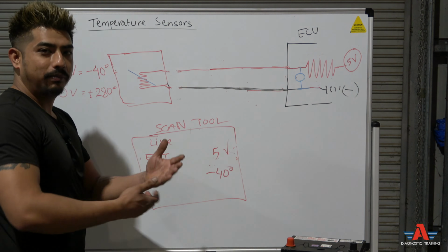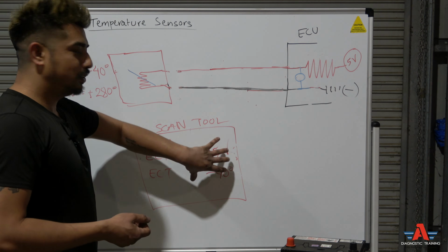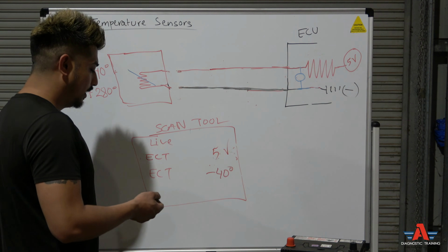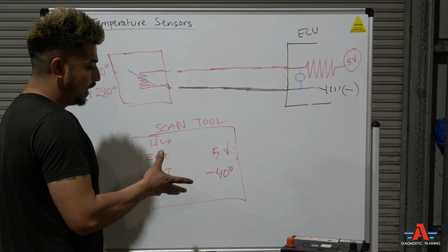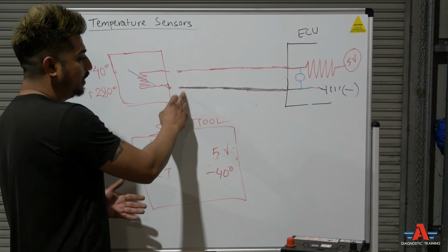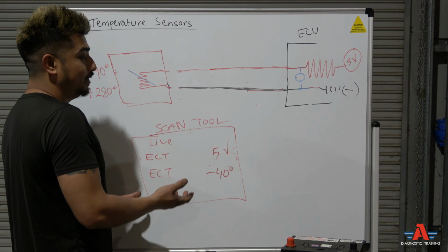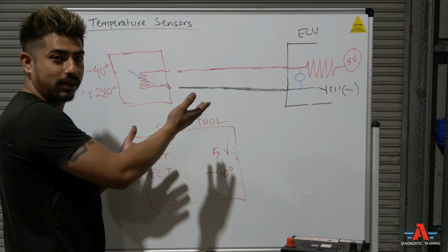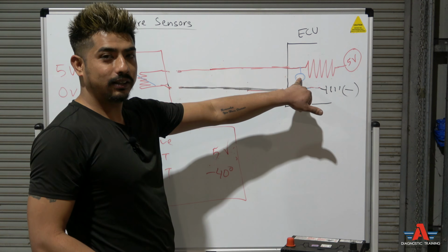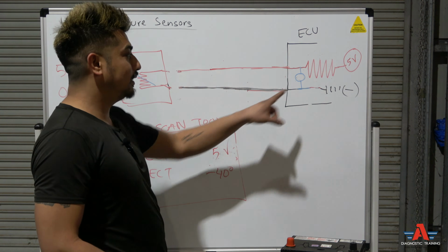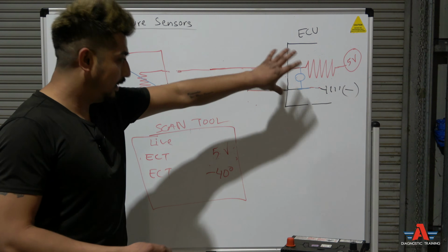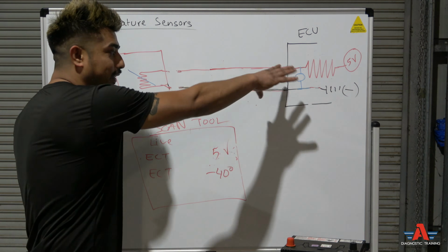With the coolant temperature, as the engine warms up, you need to see some kind of voltage changing, temperature changing, right? You didn't see anything like that. You verified there's a 5 volt, you verified there's earth, the sensor is good, you already changed the sensor. Sometimes you could have a problem with the sensing circuit. Even when everything is intact, the sensing circuit is not reading true. There's something wrong in that circuit, in that hardware.